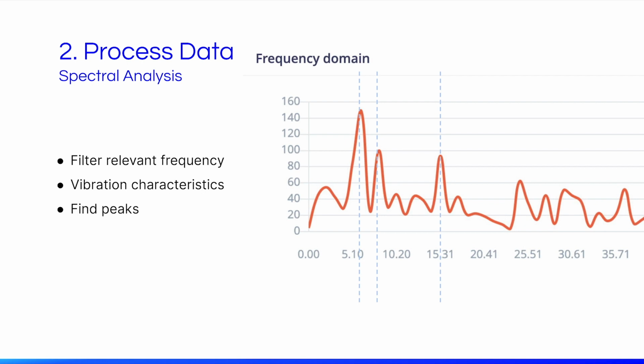In Edge Impulse Studio, when it processes the data, it turns the data from the accelerometer into a frequency domain. So you can see at which of the available frequencies in the data there is the highest amplitude, so the highest amount of motion.